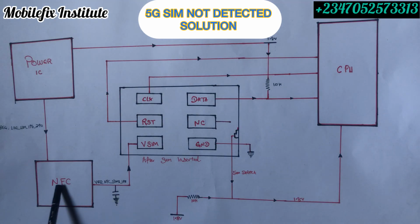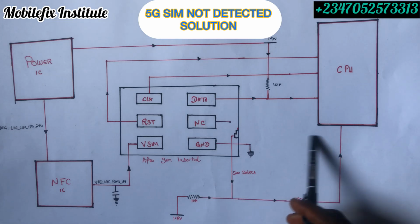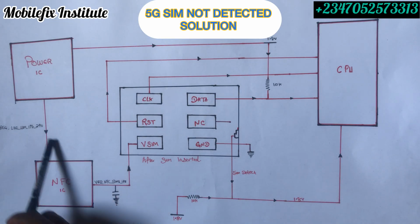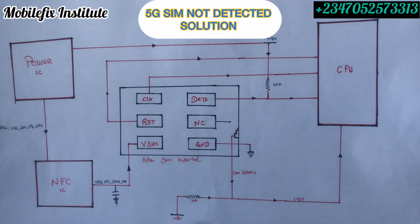So now this NFC IC, you can only see this NFC IC in your 5G phones. Most of the 5G phones have this NFC IC, but on our normal 4G phones, they will not put this NFC IC. They will just connect it from this pin to your power IC. But in case you are working on 5G phones and you see this NFC IC, don't panic, okay? This is how this line works.